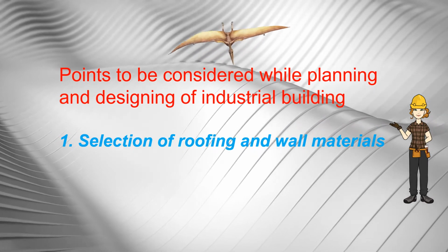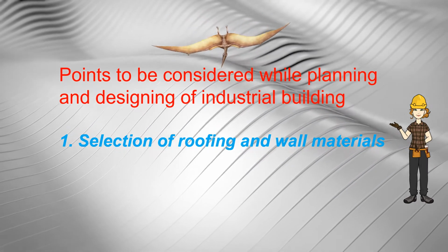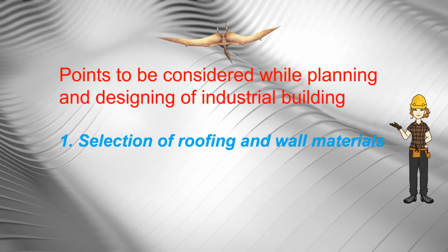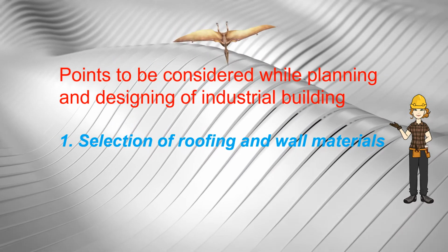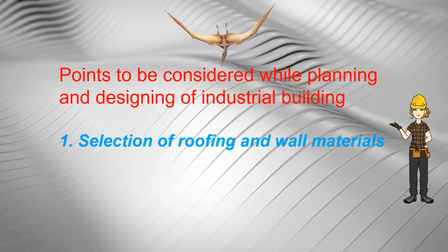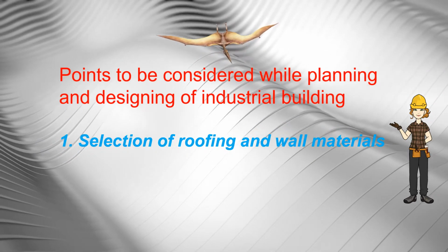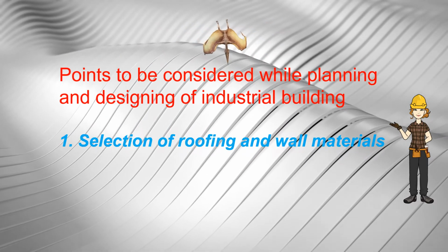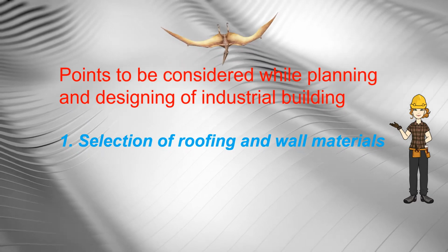Corrugated galvanized iron or GI sheets are usually adopted as coverings for roof and sides of industrial buildings. Light gauge cold formed rib steel or aluminum decking can also be used. Sometimes asbestos cement sheets are also provided as roof coverings owing to their superior insulating properties.